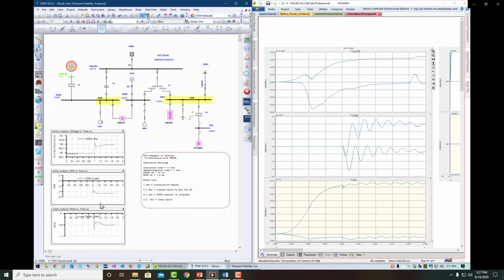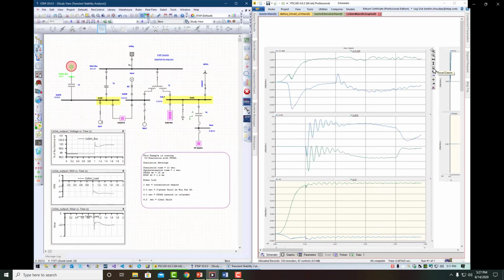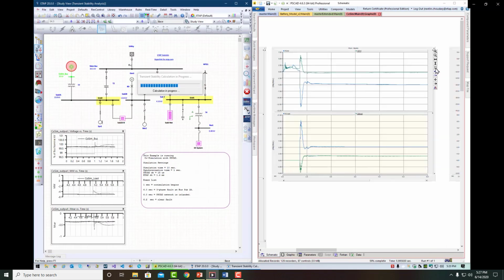At time equals 6, there is a fault, a 3-phase fault at bus sub 2A on the Phasor domain side. This causes the microgrid to separate from the Phasor domain and become islanded for the rest of the CoSimulation. After this event, and due to the breaker action, both electrical networks become independent. No data is exchanged between them anymore.